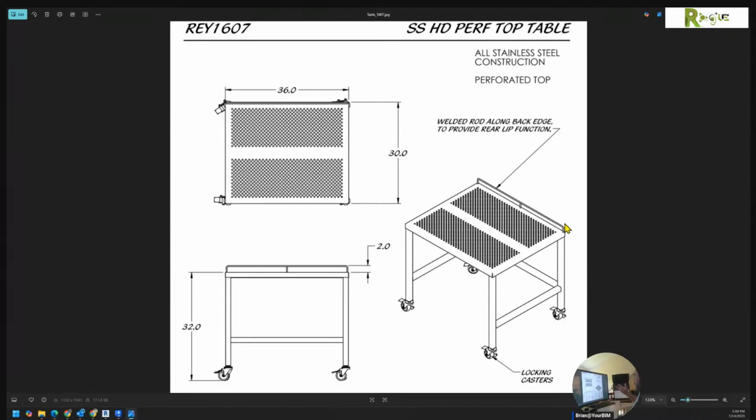Because how do we build that rail? Just as a generic model? As a generic model line-based, generic model face-based, generic model. Which one of those do you want to build it as? That's the problem you're going to struggle with when you try to look into building these subcomponents, because no one's ever really discussed it. Okay? What you're going to end up finding out